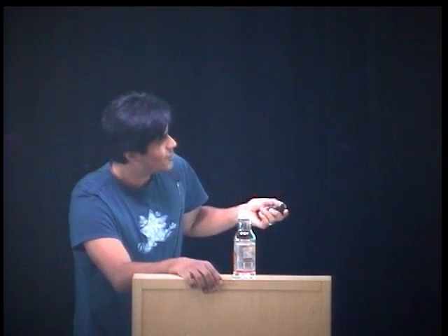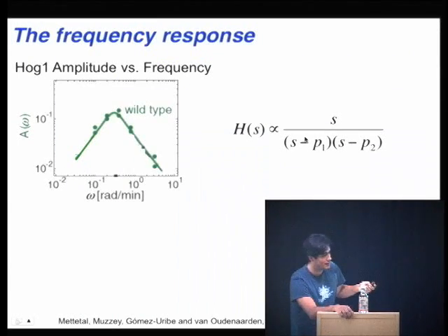You can tell, for example, that if the system is linear and time invariant, which it's not, but just as a thought exercise, a very useful one, you would know that the Laplace transform of its impulse response would have two poles at the frequency where the slope changes here. And you would also know that the system has a single zero at 0.